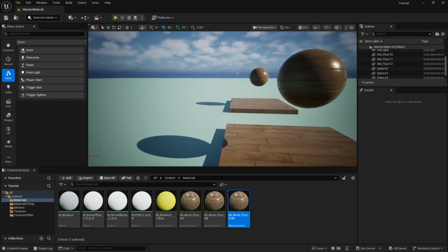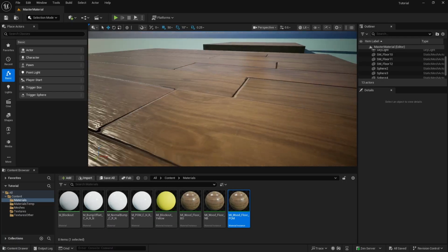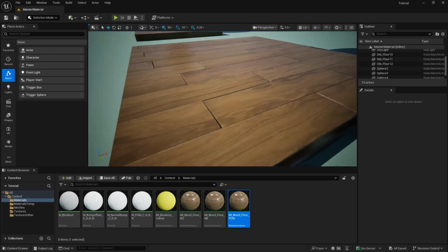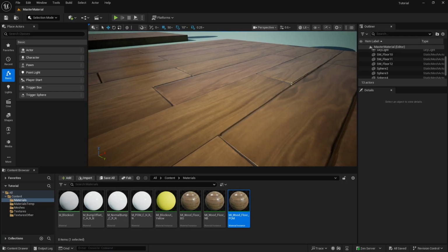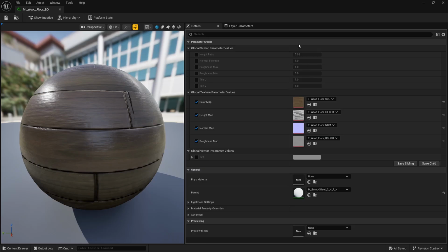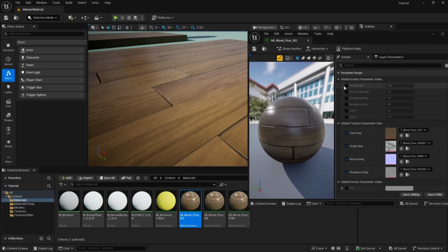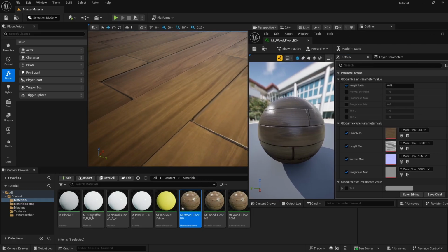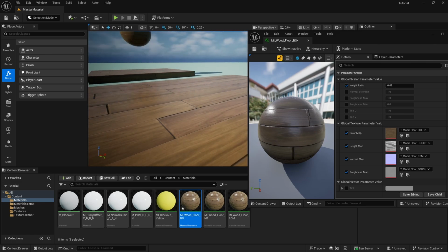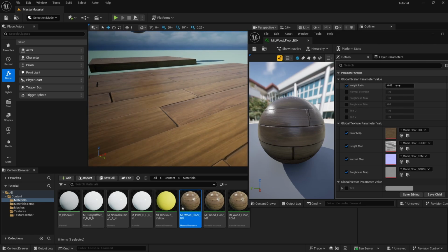Now let's go over to bump offset. With bump offset, it tries to bump it up a little bit more. It's set funny right now, so let's open up our bump offset. Right now we have the height ratio set at 0.02, which is obviously too high because you can see it's starting to pull things apart a little bit. So let's try 0.01. There we go. That looks better. Let's save that.